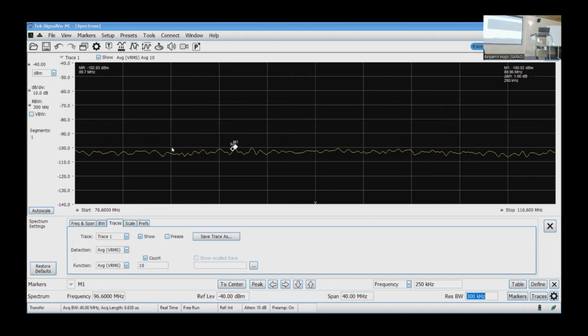Then you're going to use also, and then when you talk conducted emissions, you must also know the frequency range. It's always in the kilohertz to a few megahertz because now it is current. So you change.